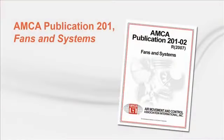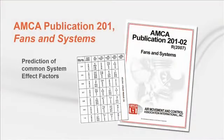As I mentioned, a system effect prevents the fan from operating as it did under laboratory rating conditions. But generating a new fan performance curve for every possible system effect would be too cumbersome and confusing. So for simplicity, AMCA has published system effect correction factors to help design engineers account for many of these effects before the fan is selected and installed. These correction factors are like effective pressure drops that are added to the estimated static pressure loss for the rest of the system when selecting a fan.